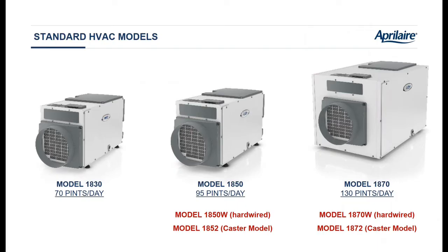All right, let's talk about the models a little bit. There's 3 basic capacities: 70 pints per day, 95 pints per day, and 130 pints per day. All dehumidifiers are tested and rated at the same conditions: 80 degrees Fahrenheit and 60% relative humidity.